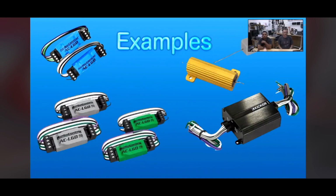Here are examples of load resistors. The most common ones that we use, or the two that we stock, I should say, are all the AC LGDs, which you have the AC LGD blue. These are real popular for Fords and cars that don't have the turn-off circuit. This will work fine. The new Chevys, however, all need the greens. And then the amplified Chryslers work off of the gray.